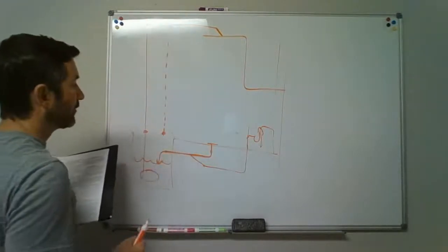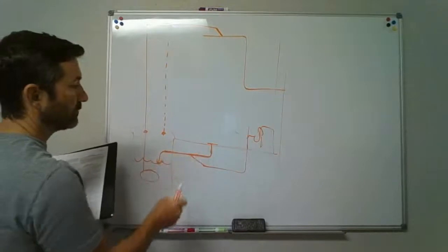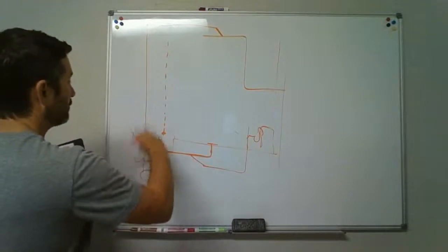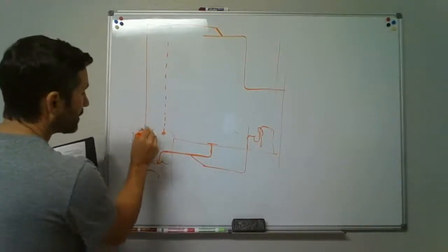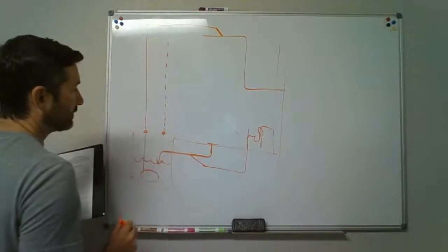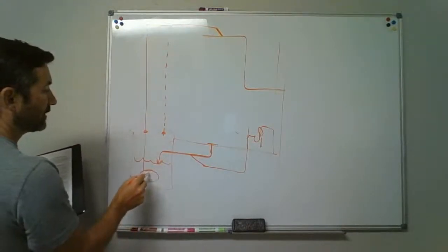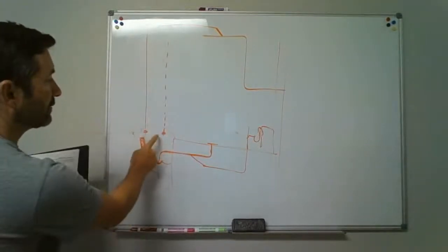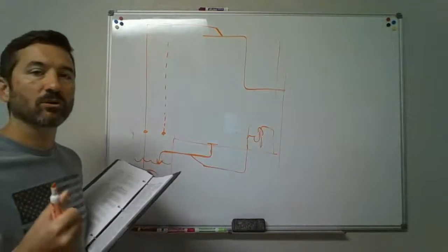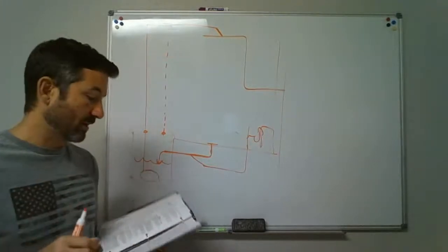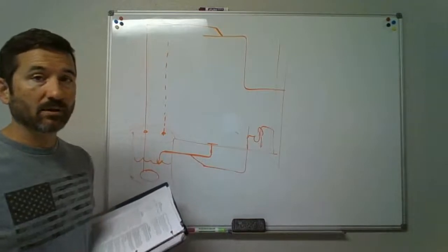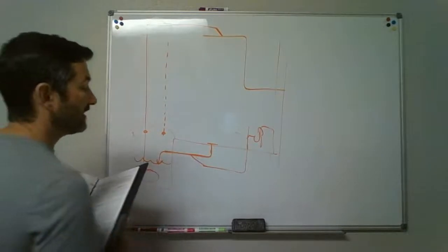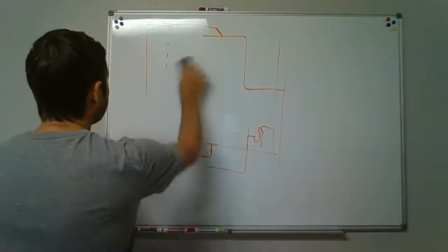Otherwise, what you might hear is some gurgling and bubbles coming up into your toilet or other fixtures, because of the air being pushed out. So we need to be able to breathe both ways. When the pump kicks on and starts pumping that out, then it's drawing air into the tank. Can't use an air admittance valve here, and you can't use the air admittance valve for your main vent. You still have to have a main vent that goes out to the open air and is breathable. But pretty much everywhere else, you can put an air admittance valve if you wanted to. As for the location, they have to be at least 4 inches above the fixture arm.